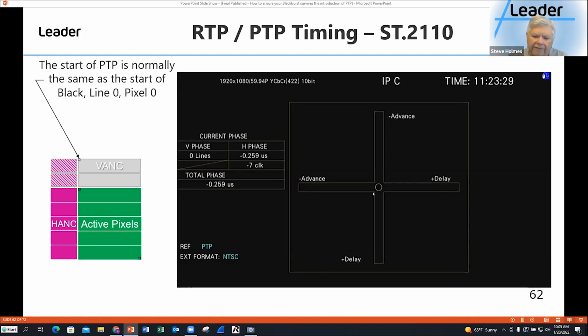So you have to lock the two generators together with either Black or PTP. You have to pick one that's going to be your grandmaster. It's going to lock the second unit so they're both in time with each other. And then they will both be clock class 248, but at least they'll be in time with each other.